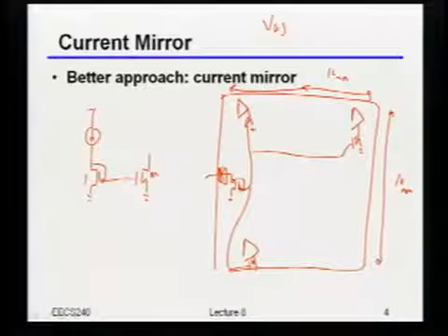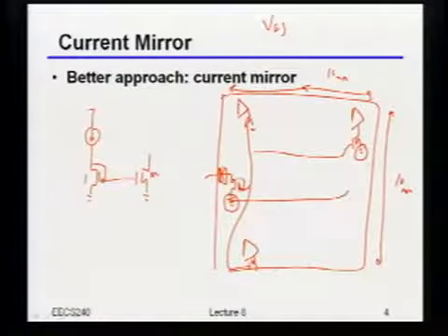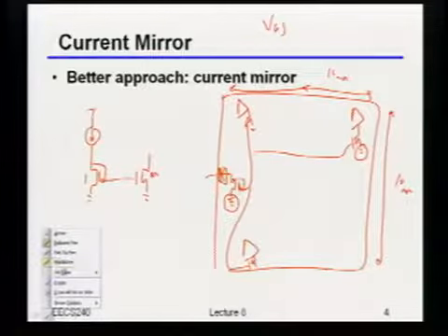Okay, so remember, anytime you measure voltages, there always have to be two points, right? As an example, what I called ground right here is not really going to be the same as the ground over there. Because in reality, there's actually some ground wire going like this, and maybe let me draw it in a different color so that it's clear.